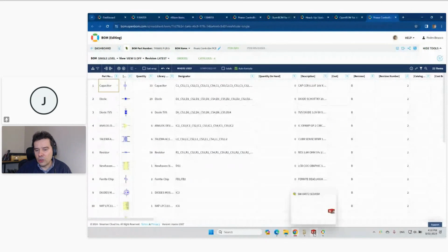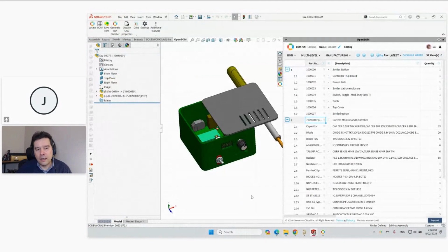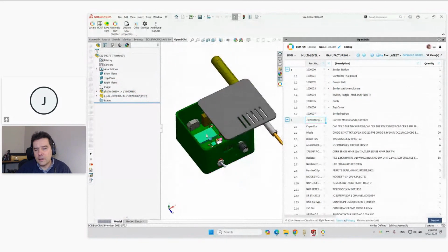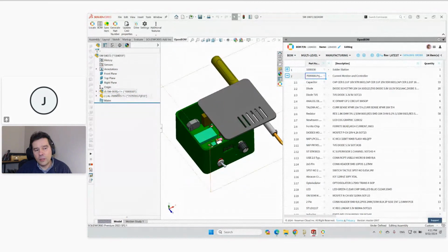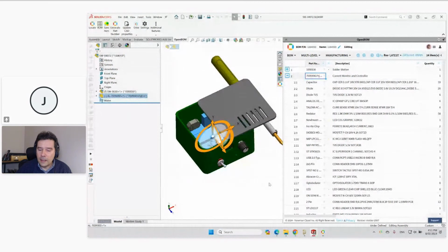Now we can do the same for SolidWorks. And notice that the PCB component is actually inside the SolidWorks bill of material. So I have extracted that component. It is a PCB part file. And how do we link the two? As we can see here, you can actually see the complete bill of material inside SolidWorks. From SolidWorks, you only went to the part level, but then all the children were populated by the Altium integration. So here is where you see a complete product structure, where you have two different design sources.